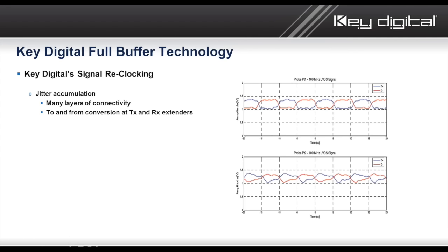You'll see this as part of our full buffer technology, TMDS reclocking. Why is that? Well, the top shows you an open eye diagram of a healthy HDMI signal. Ones and zeros, ones being the lines, zeros being the open space in between, the open eye, if you will. And beneath is after a long HDMI run, you see the ones and zeros aren't clearly defined anymore to the sink device, the television at the end.